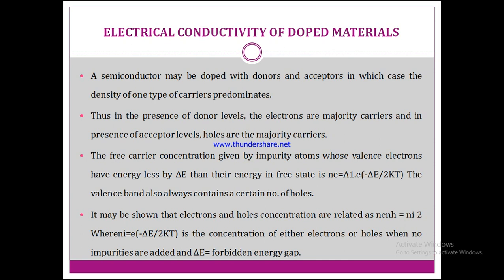We identify the type of material, whether it is a conductor, insulator or semiconductor, with the same equation. For example, a substance for which the energy gap delta E is 100 or 200 times the value of kT will be an insulator. But if delta E is less than or equal to about 40 times the value of kT, then it will be a semiconductor material.